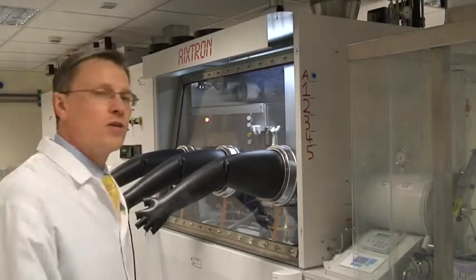Coming back to the tool here, you may notice the cabinet is quite long. The far end of the cabinet contains all the plumbing effectively to control the gas flows to the reactor. That means we need to have very strict control over the flow rates and the temperatures at which the gases flow into the reactor, in order to maintain our high quality.